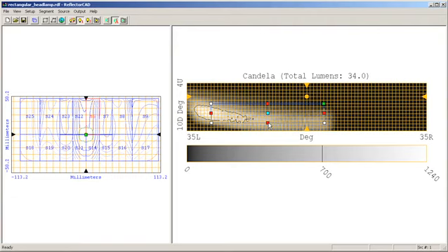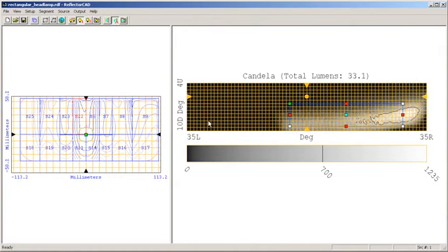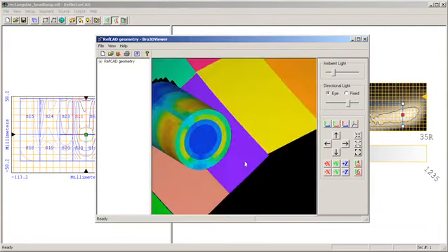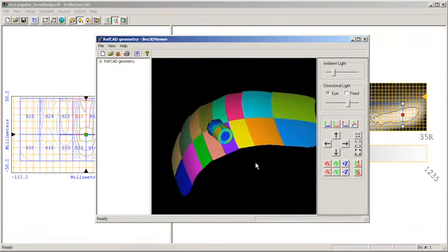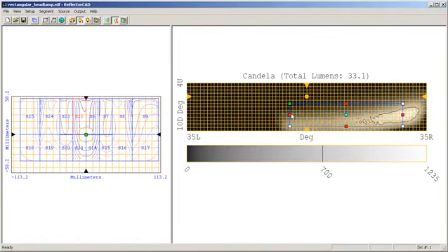ReflectorCAD then automatically will adjust and create that segment corresponding to that particular radiometric output. ReflectorCAD will also automatically fill in the spaces between segments with inter-segment fillers and allow you to 3D visualize the reflector, source, segment shadowing, and inter-segment fillers. The resulting reflector segmentation geometry, including inter-segment fillers, can be directly output to ASAP for further detailed engineering design and analysis, or to an IGES file for use with the CAD package.